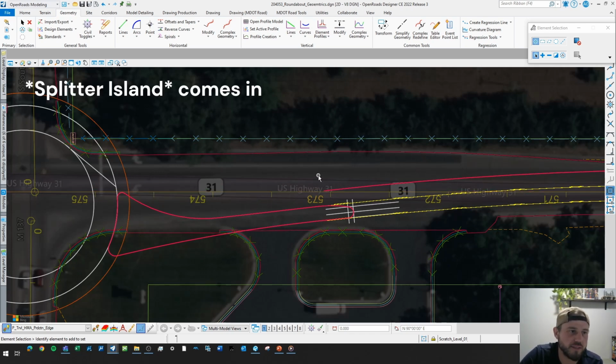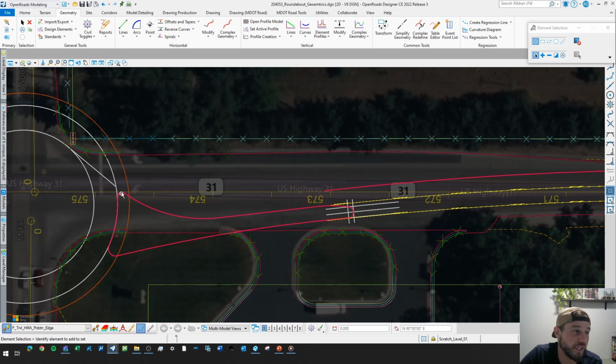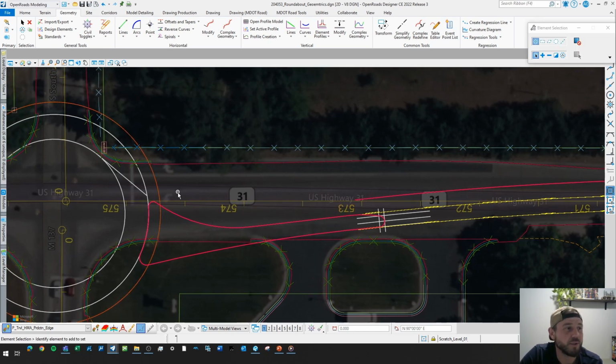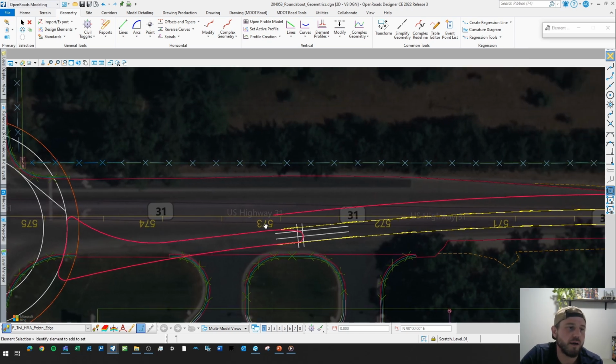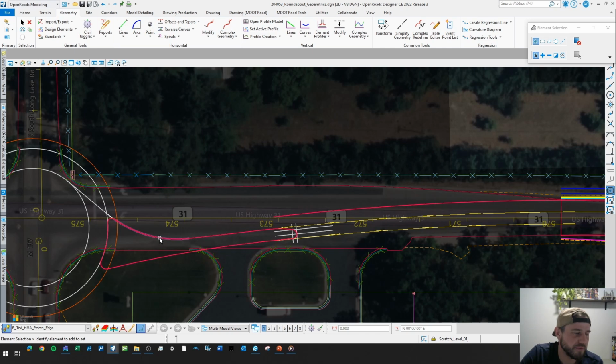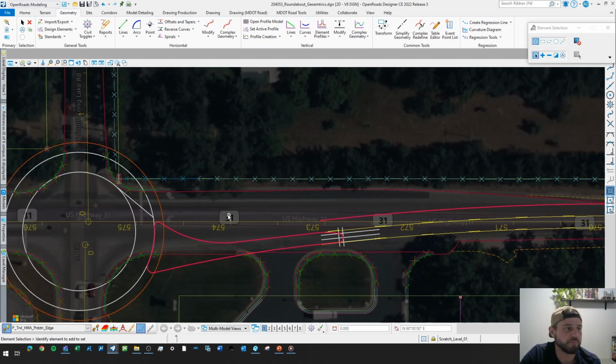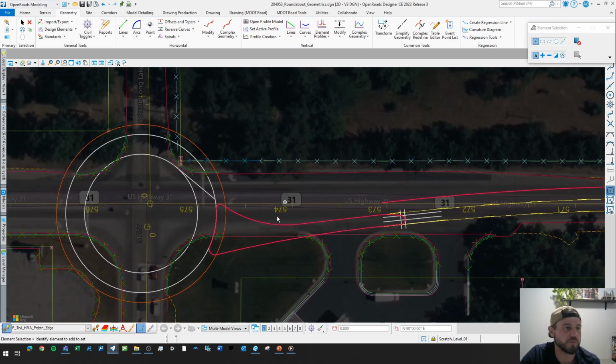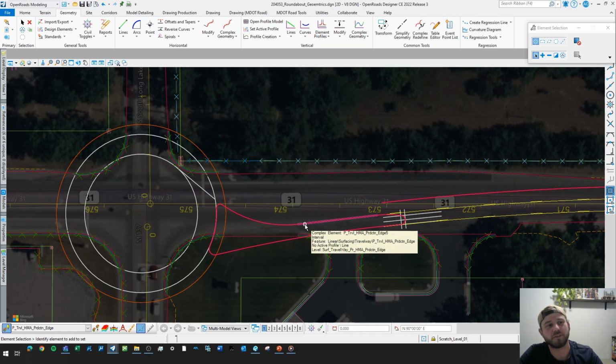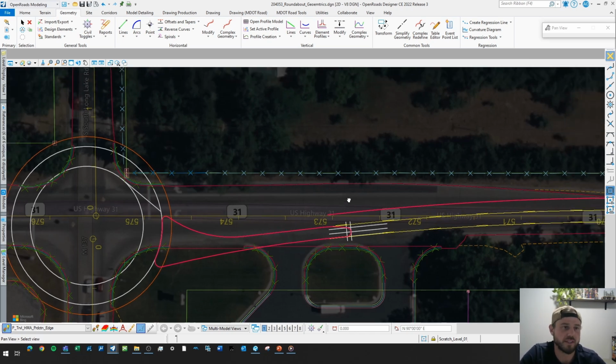But from my experience, even for a single lane, this is typically 14, and it widens between 16 to 20 feet for the entrance, depending on that design vehicle. And again, you're fighting two different things here. The curvature is great for speed on a passenger vehicle and keeping those volumes low, which is good for safety and everything else. But that curvature also directly affects your ability to get the design vehicle through. So it's that balance between.